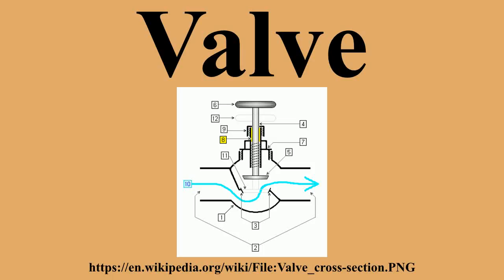97/23 EC. Some fluid system designs, especially in chemical or power plants, are schematically represented in piping and instrumentation diagrams. In such diagrams, different types of valves are represented by certain symbols. Valves in good condition should be leak-free. However, valves may eventually wear out from use and develop a leak, either between the inside and outside of the valve or, when the valve is shut to stop flow, between the disc and the seat. A particle trapped between the seat and disc could also cause such leakage.